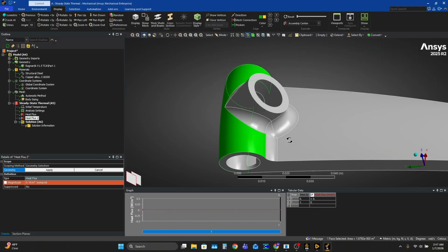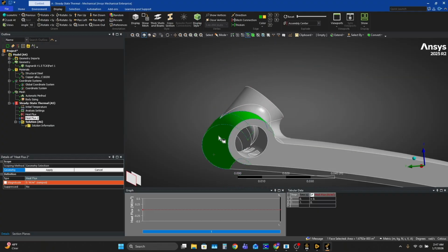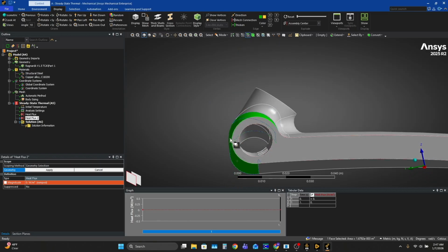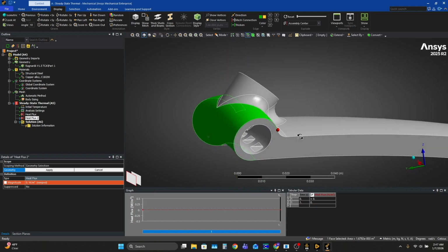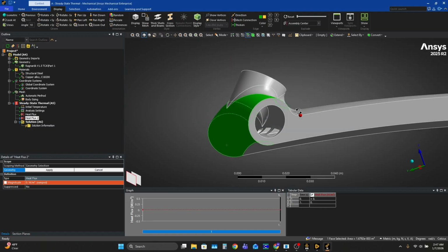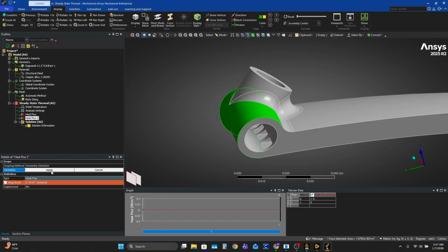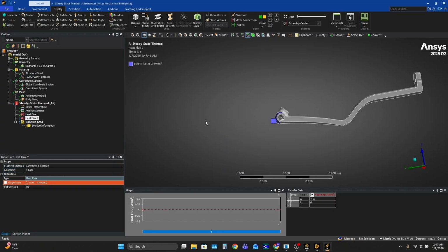The problem with applying this heat flux load to the annulus is that the annulus geometry wraps around the entire thing. In reality, we would really only see heat flux load to about the midpoint. This can be revised with future revisions of the parametric TCA, and hopefully we'll do that in the future, but I have not done it yet. So for now, we will just apply a simple distributed load here.